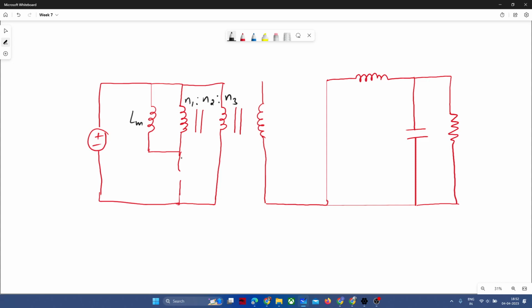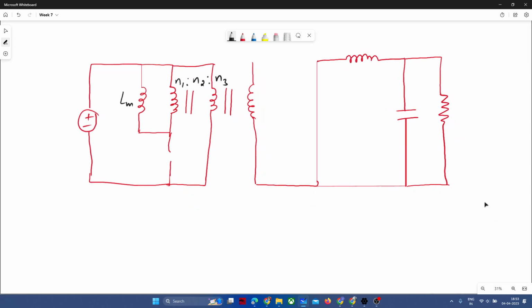But here we are trying to analyze and we have to play with the magnetizing inductance, so we must show the magnetizing inductance in this circuit. Even if you show the approximate equivalent circuit of a transformer, an ideal transformer or any transformer, you will provide a separate magnetizing inductance, and that magnetizing inductance is the notation of the parameter: how much magnetizing current, or how much portion of the power, is getting distributed in the process of magnetizing the core. So magnetizing inductance is an important parameter. We denote it separately in all kinds of circuits. It is up to you. If you want, you can eliminate it, but generally we show it. So it's all nothing but assumption, in whatever way you want to express it.